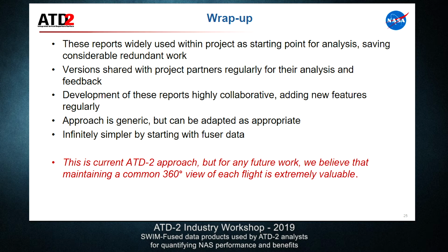So we've adopted a geometric approach where for each runway at each airport, we have a box. Once you enter that box, you're in the queue. So if the queue gets really long, we're not going to accurately capture when the flight enters the queue. If the queue is really short, we're going to overestimate taxi time by some number of seconds when the flight taxis over that entry line and then eventually stops deeper into the queue. So it's an approximation.